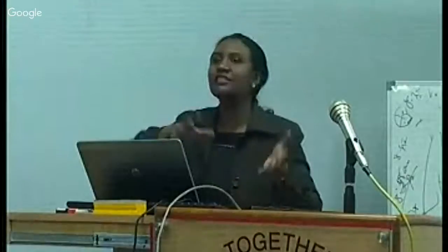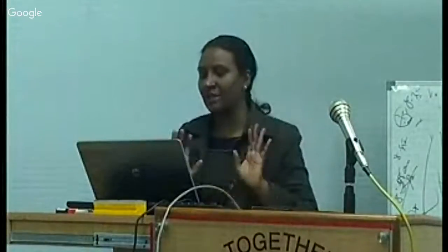So here, other things you can remove. What I showed you is a system with this multi-level inverter. When you implement it in real time, what is required? Your multi-level inverter will be there in real, your motor will be there in real, and your controller is also there. In the controller, what will you flash? This neural network. This is required for your final hardware implementation. All the other things will be in real, and this will be in your hardware.